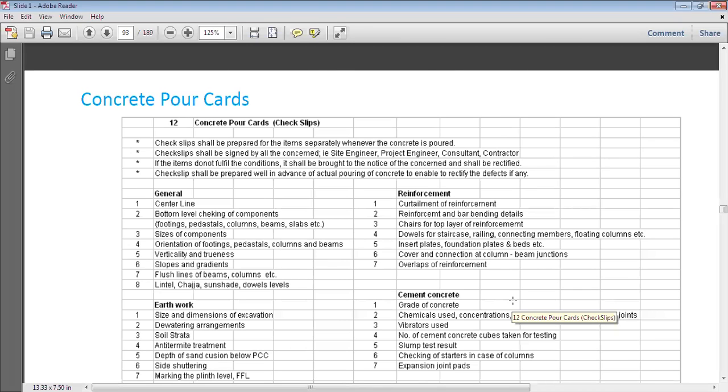There was no awareness or invention of higher strength, high strength concrete grades. So at that time they used M15 grade concrete for the footing work, or for the foundation. Nowadays also, in some very rare cases, you observe that they are using M15 grade of concrete for the foundation. But nowadays we have the practice of using M20, M25 grade generally for our construction purpose.